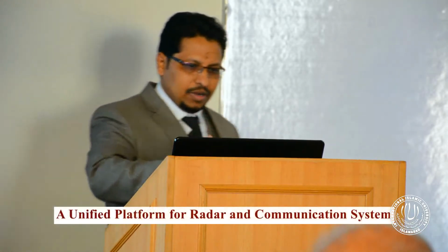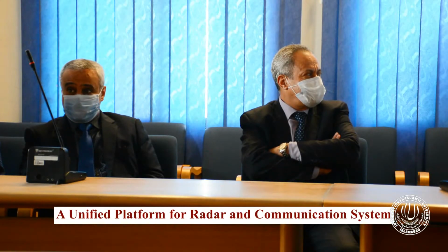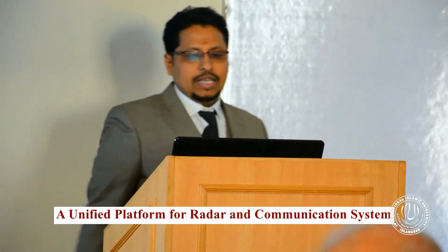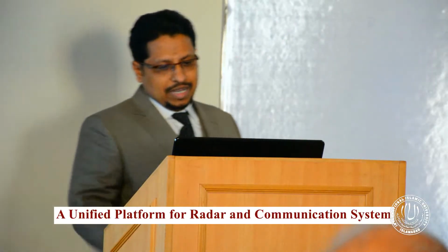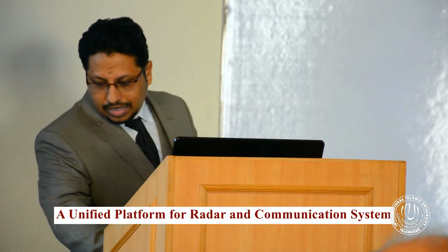So we have zeros at z1, z2, z3 as shown in equation number 8, after we give it a coefficient weight vector in equation number 7, then we transform this to factorized form as shown in equation number 8. So our array factor in factorized form can now be transmitted.